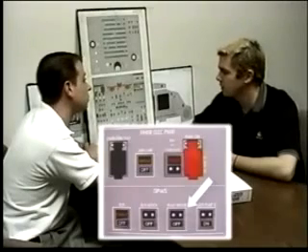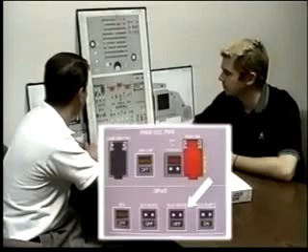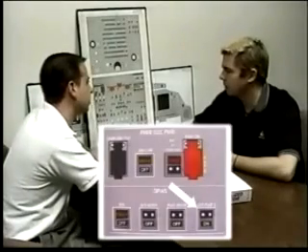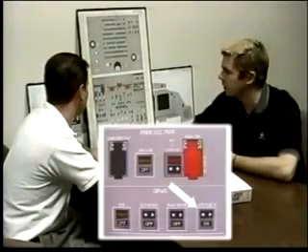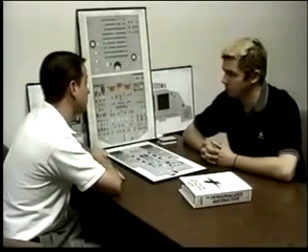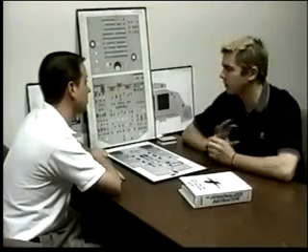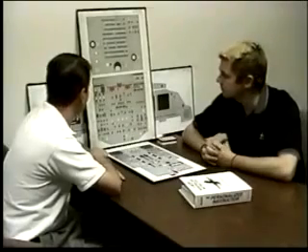It prevents the too low flap GPWS alert. Finally, landing flap 3 on. Landing flap 3, I select at any time I'm doing a flap 3 landing. What that does is it suppresses the landing flap GPWS when it expects full flaps. What it also does is it allows the landing memo to change to green when I get flaps 3 instead of staying blue waiting for flaps full.